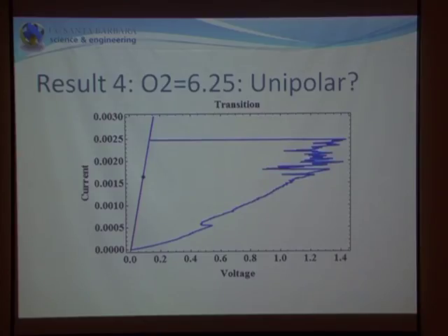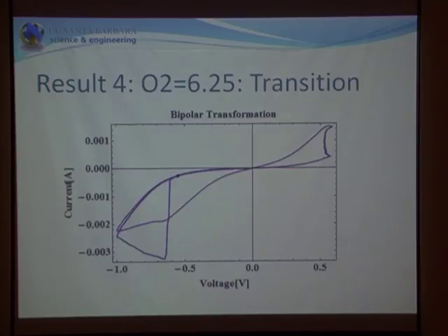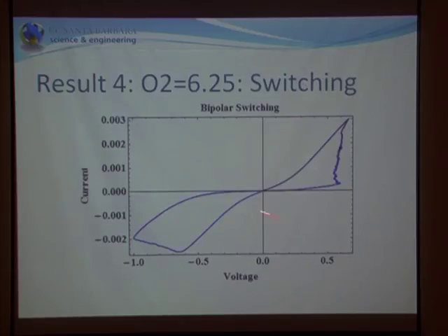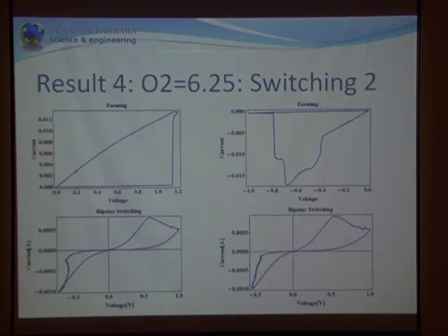And now if you're extra clever, and you do a voltage-controlled sweep, you can actually put it into a bipolar transition state because you turn it on and then you immediately start to turn it off. At least that's what I think. And you have this kind of bipolar switching in this nice, fairly vertical climb. This is a kind of a better device, and as you can see, you have actually better on-off ratio than in the previous devices. And the switching is fairly interesting.